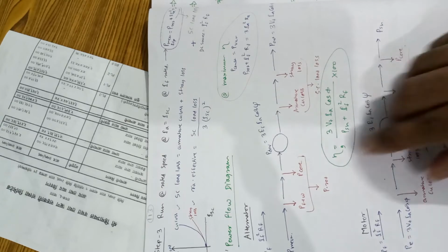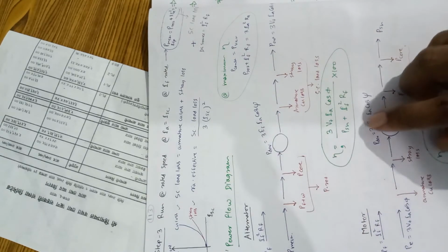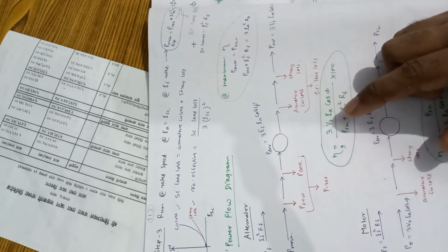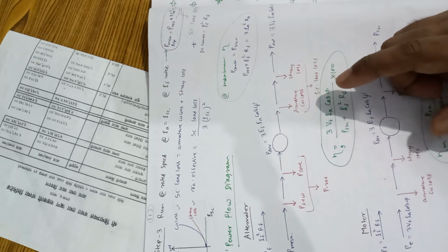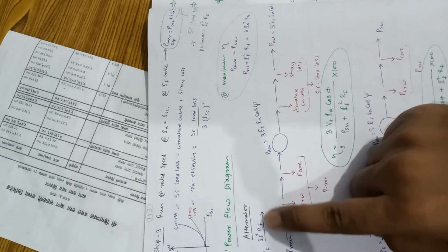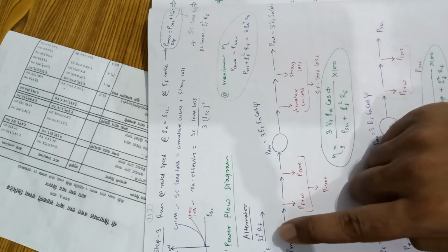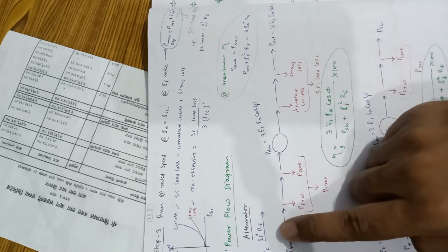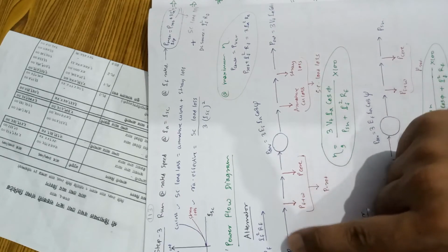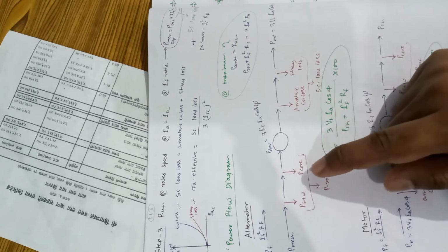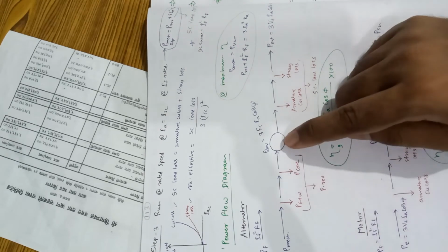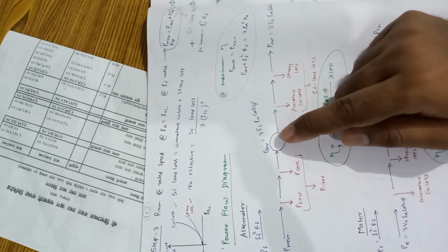So when we talk about the power flow diagram of alternator and motor, see here we have the power flow diagram. This we have alternator. For alternator, what we give as input is mechanical input plus field excitation, P mechanical plus field input, IF square RF. After giving these two inputs, what we first see is rotational loss, that is friction windage loss plus core loss, and then whatever power is obtained, that is developed power,